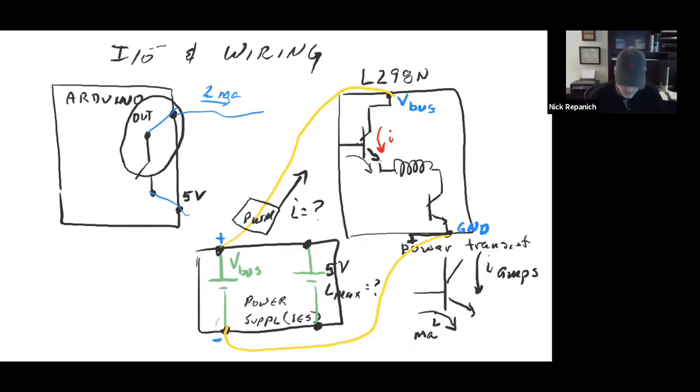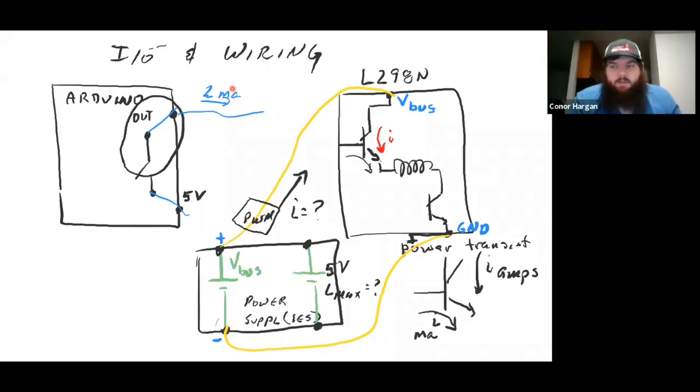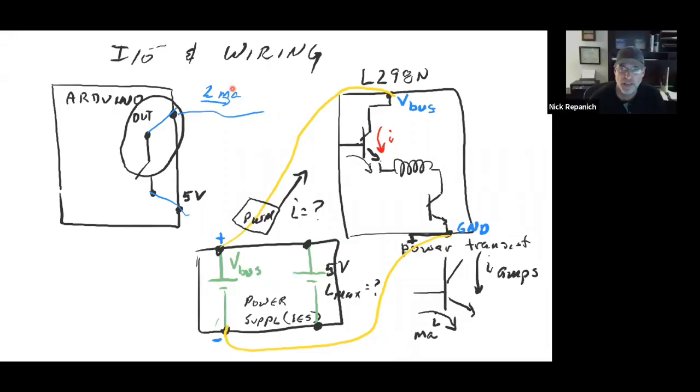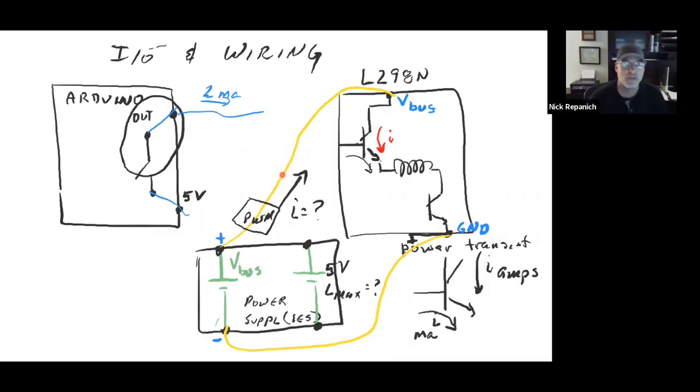So stop doing that. But a 2 milliamps is a different wire. How big of a wire do you need for 2 milliamps? Like 24 gauge or 26 gauge or something? There you go, 24, 26 gauge, right. How much do you need for 2 amps? 18, maybe. I don't have an Ugly's book handy, but exactly. But you're on the right track. 2 different numbers, right? 18 is probably good.